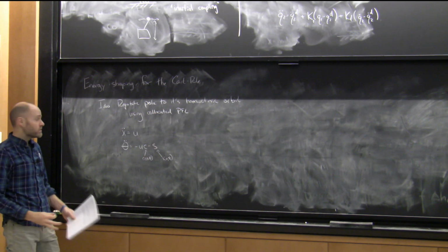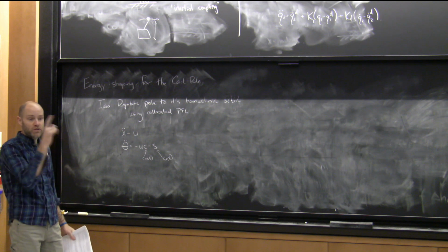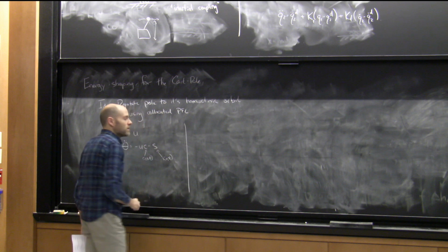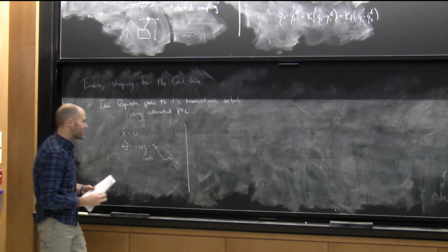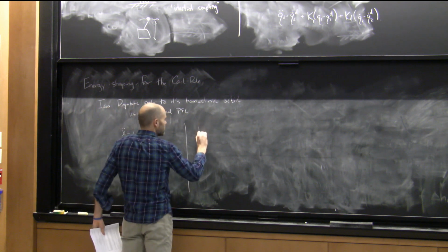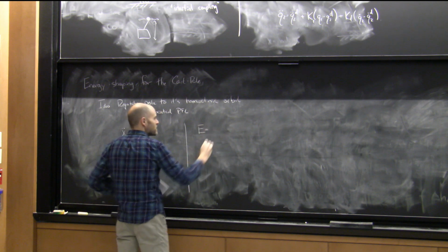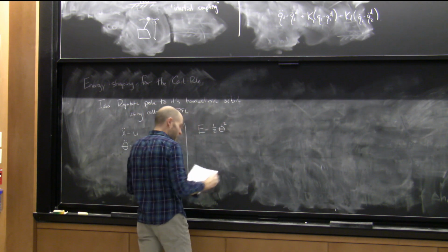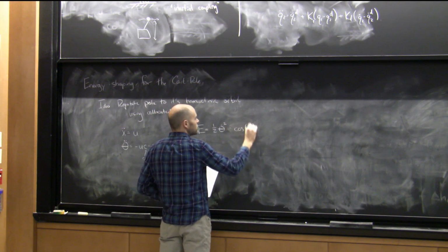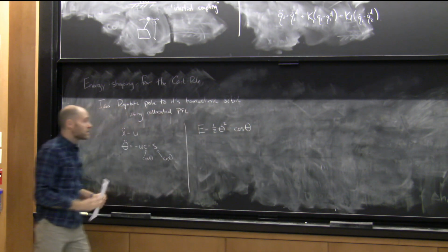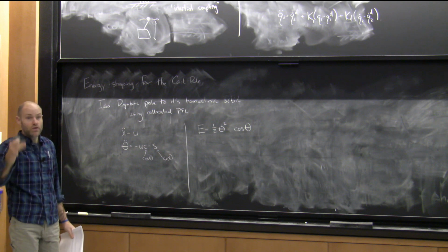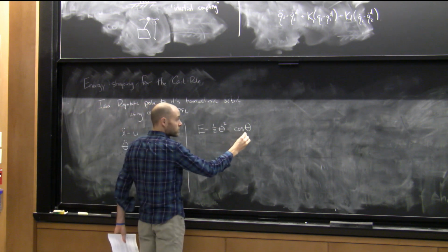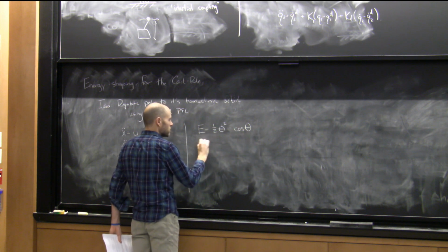So the homoclinic orbit was the orbit of constant energy. We're going to just think about the pole alone. I've set all my masses and lengths and gravity to 1, which meant that my energy was theta dot squared minus cos theta. My desired energy for that homoclinic orbit, in this case, is just 1.